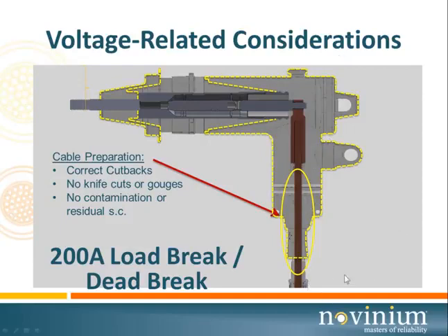Why do we do that? If you wipe with a solvent in this direction, from the cable shield down the insulation, we're going to drag carbon particles from the insulation shield here, and we're going to drag it down the surface of the insulation and contaminate things even worse. So now let's assume we've got no contamination, everything's clean, ready to go.